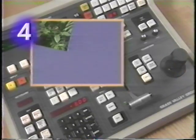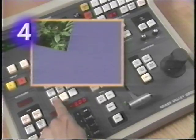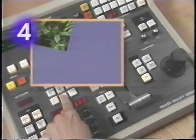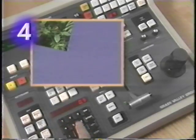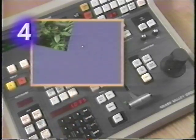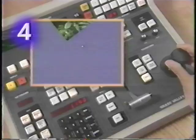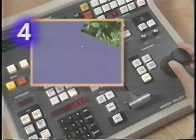Now let's use the direct entry keypad to define our orbit. Orbit values are entered as complete orbits, plus a percentage value of an orbit, with a decimal point separating the two numbers. Positive values orbit the picture in a clockwise direction. Negative values orbit it in a counterclockwise direction.